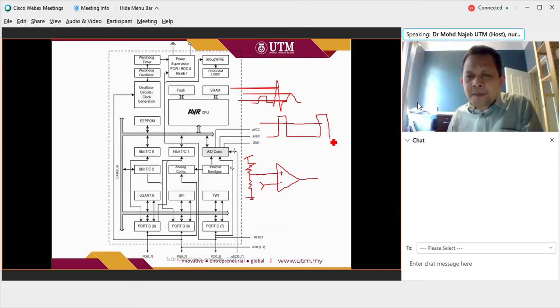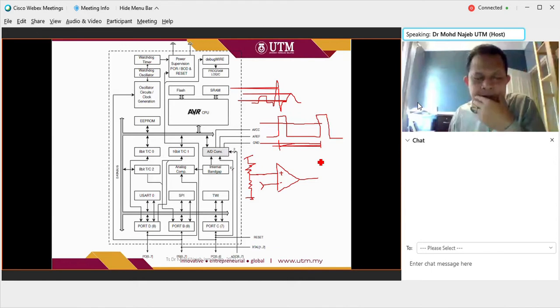For the first trigger, you capture the time, and after a certain time, you get another pulse from the analog comparator, and then you capture the time. This is an example. From here, you can calculate the time between these two pulses, which represents the time between the peaks of your QRS. From there, you can calculate your heart rate.